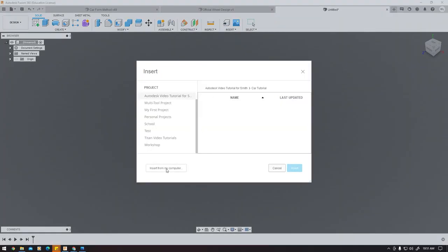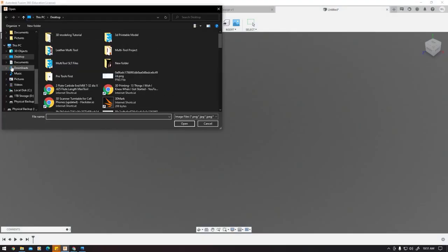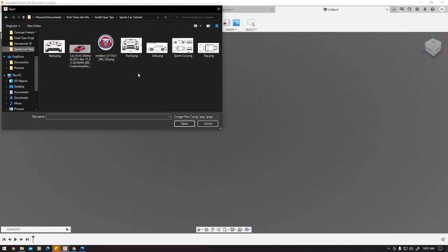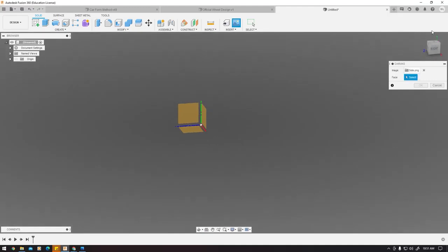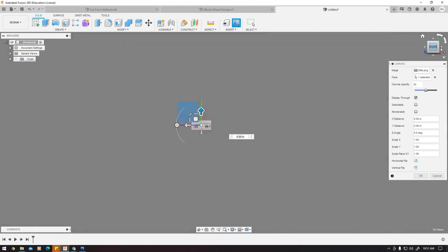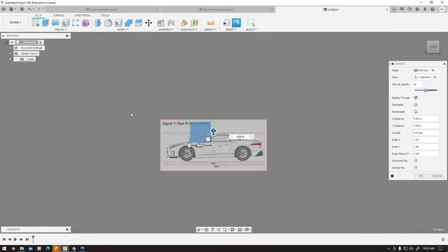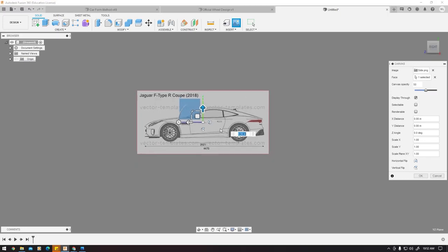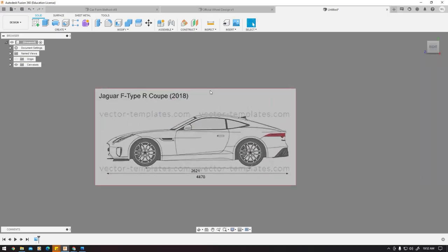We have to do this one at a time to get our sides correct and our calibration to spec. I want to start off with doing our side view, so I'm going to click the side view. As we see on our Rubik's Cube, we can just start from the right side. So go to right side, click on the ZY axis, and I click on the Rubik's Cube to get an orthographic view of the right side. So I could press OK and I'm done.